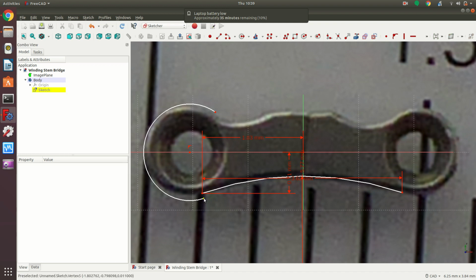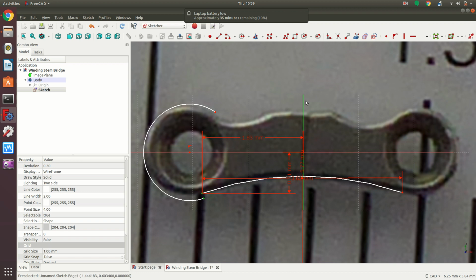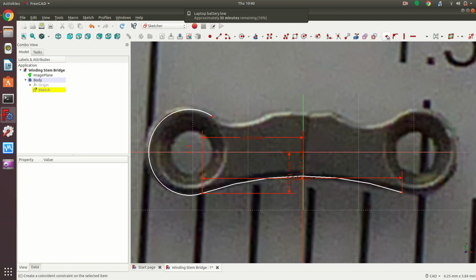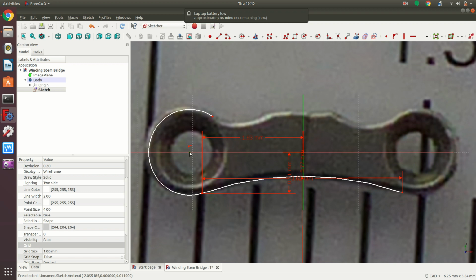We can basically force a join now. So I select the two points, and I will say there's a constraint with these two points, and boop, it moves up. Beautiful. But we can see this is totally wrong. The radius has to be more, and the center is not the center of this hole. So what we see now, we have the beauty of being able to change all this, and it's not going to muck up our base arch.